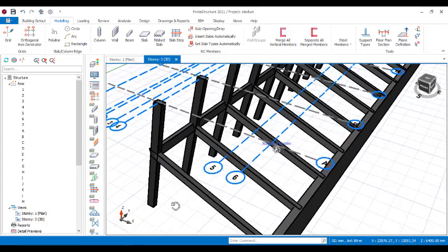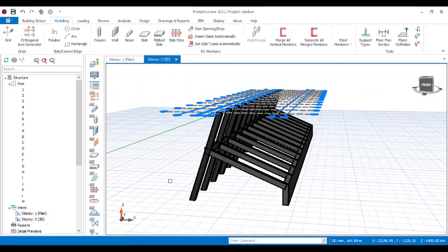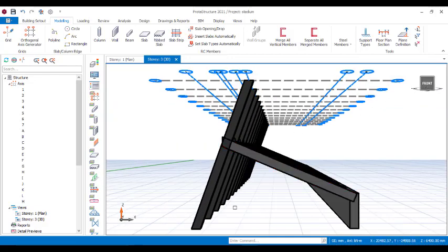All right, so the floor is supposed to be like a stair. Okay, so now we're just going to do a little bit of calculation, just a small calculation. So I'll put this in front view, so we can see this properly. The first question will be, how many steps will we have in this story? When I say step, it is the combination of riser and tread. To know the number of steps we have to say what is the thickness we want each step to be. So I want the thickness of each step to be 400 mm.